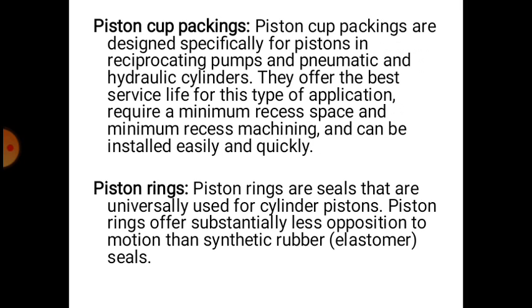Piston cup packings. Piston cup packings are designed specially for pistons in reciprocating pumps and pneumatic and hydraulic cylinders. They offer the best service life for this type of application. They require a minimum recess space and minimum recess machining and can be installed easily and quickly.